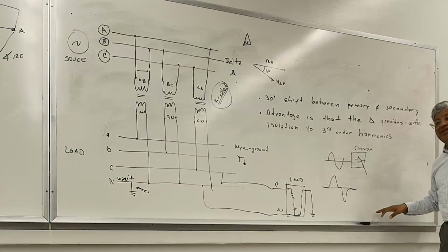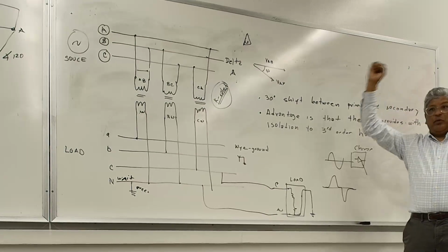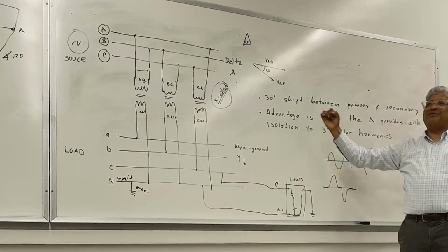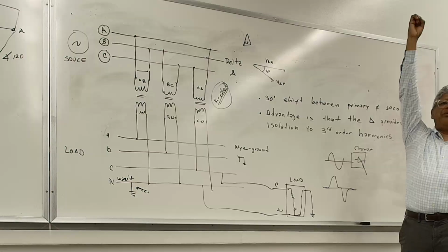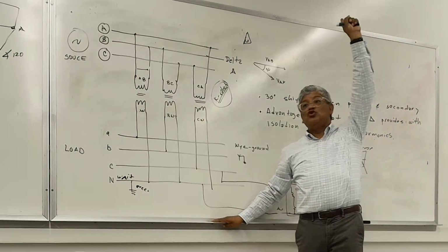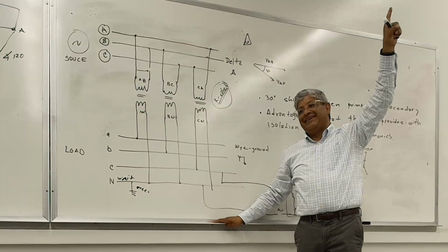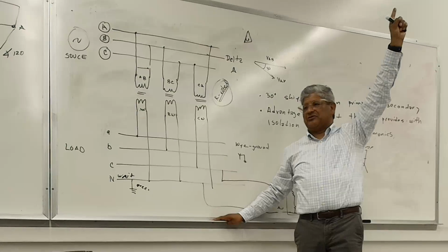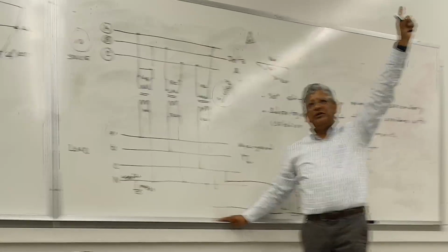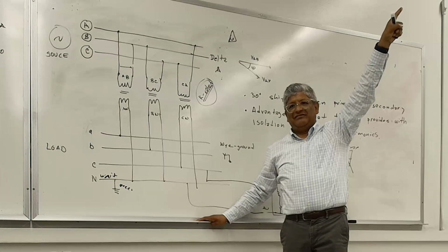If you look at transmission towers, if you go outside and look at distribution and transmission towers, you'll see 3 wires. There's sometimes a wire right on the top, and people always get confused. Right away, people say, oh, that's the neutral wire of the transmission line. That is not the neutral wire. That is a non-current-carrying conductor. The only purpose of that is lightning protection.